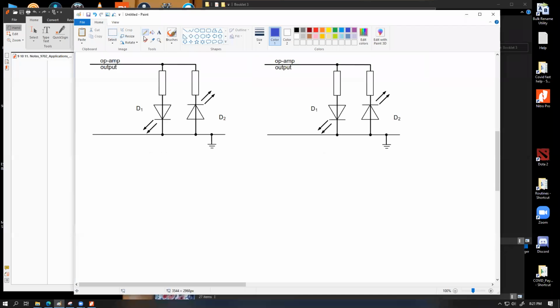So whenever the op amp output is positive, in that case this is 0 voltage, and this is the saturated positive voltage of the supply. Then current is flowing through this diode, and this LED is going to glow. You cannot choose this LED to be a very highly powerful LED. For example, it shouldn't be something of, let's say, 100-200 watt LED.